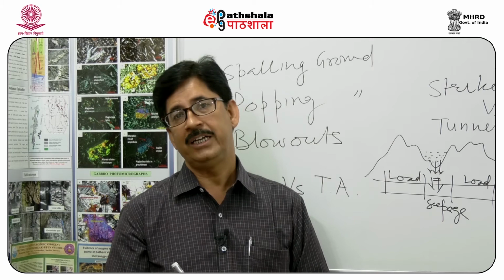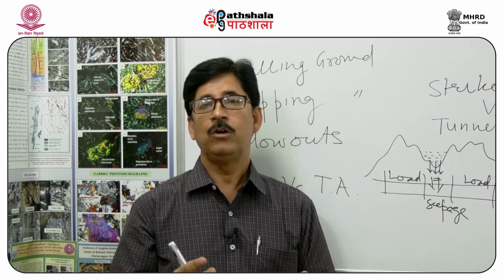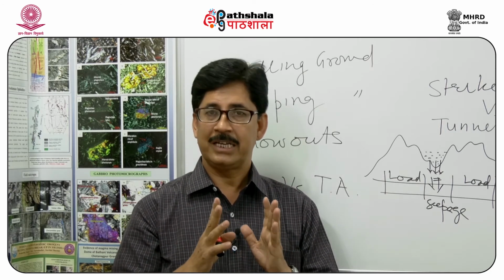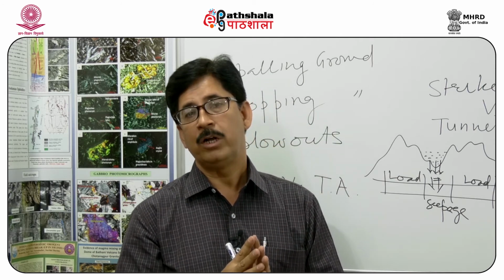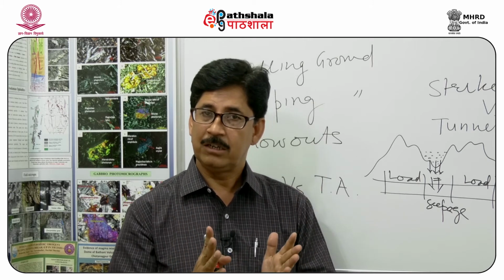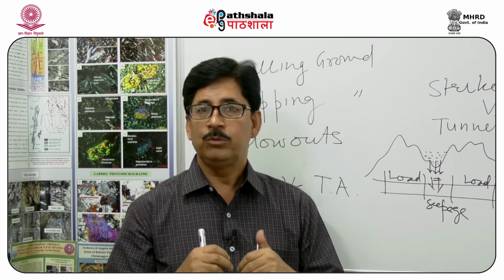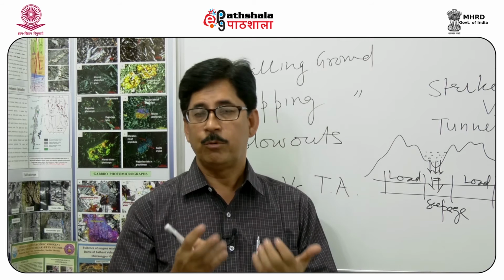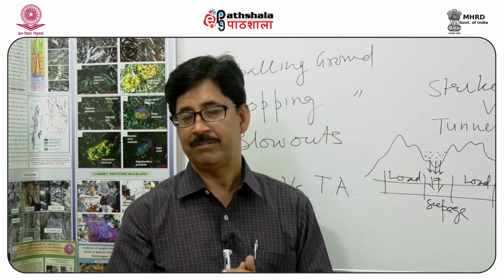They will always be there. The presence of joints is actually going to have overall control on the behavior of rock mass as far as tunneling operation is concerned. Depending upon how many sets of joints we have, what are their spacing, what are their orientation, it is all going to affect the tunneling excavation and post tunneling operation, because we have to seal all these joints and fractures.